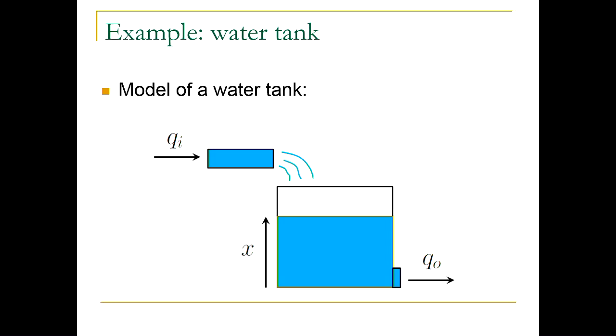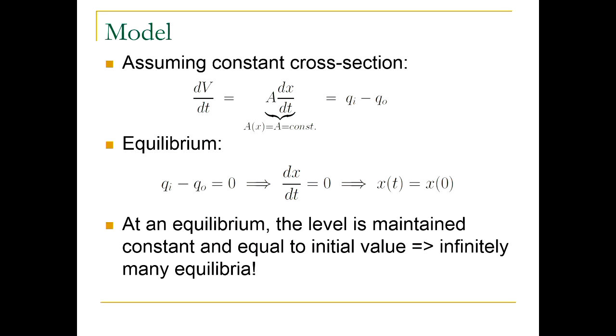Let's look at this situation a bit more mathematically. So if I assume that the liquid is incompressible, then I can apply the law of conservation of mass, which then becomes the law of conservation of volume. So basically, the change of volume of water or liquid inside the tank, so this dV/dt denotes the derivative with respect to time, right, would depend on the difference between the inflow and outflow, like volumetric flows. I'm talking about volumetric flows here.